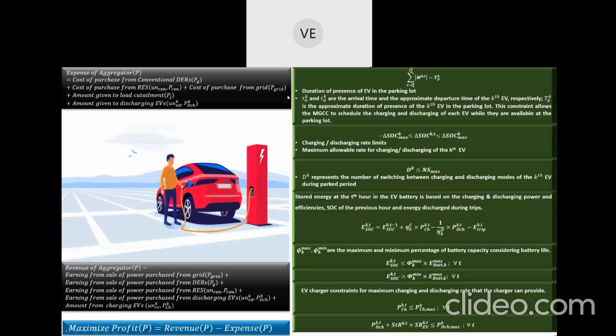Simply a deterministic variable, but what happens is, if there is an uncertainty in the power from renewable energy, it has to be balanced from the grid, right? So indirectly, the uncertainty in renewable energy reflects on the grid. So this also becomes a stochastic variable, which is a function of P REN. Okay. So if P grid is stochastic, then cost of purchase from grid is also stochastic. That means this is also uncertain. So each term is now becoming a stochastic variable.